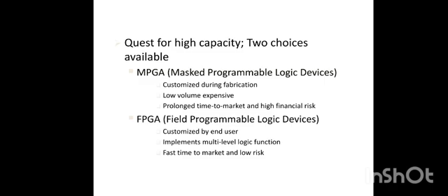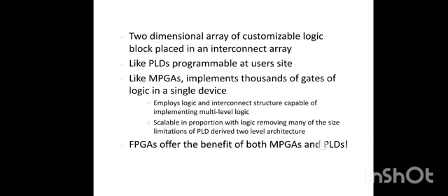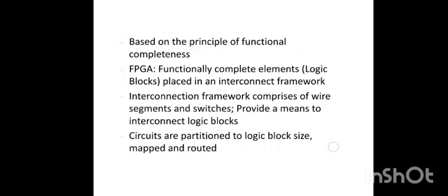So we introduced FPGA, field programmable logic devices, that is customized by the end user, implements multi-level logic functions, fast time to market and low risk. A two-dimensional array of customizable logic blocks placed in an interconnected array, like PLDs, programmable at the user's side. Like MPGAs, it implements thousands of gates of logic in a single device. It employs logic and interconnect structure capable of implementing multi-level logic. FPGAs offer the benefits of both MPGAs and PLDs.